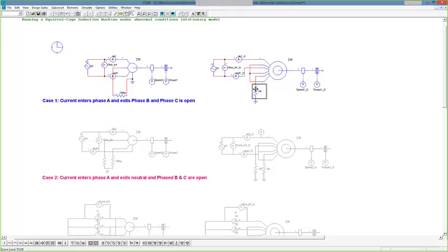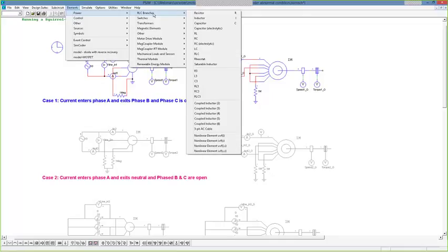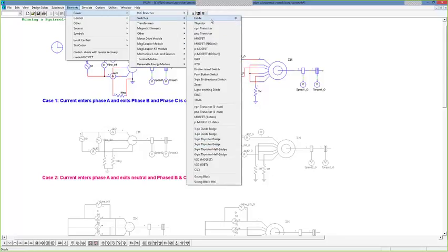So with PSim here, we can see there's a resistor. In the elements menu, it's defined this way. We have RLC branches here. Down at the bottom are some fun nonlinear elements. In the switches menu, there are the basic models, and then they get a little more complicated near the bottom. We have a 3-state MOSFET, and I can show you our characteristic MOSFET as well. Now the thing with the switches is you need to drive them with a gating block, and I'll get to that.